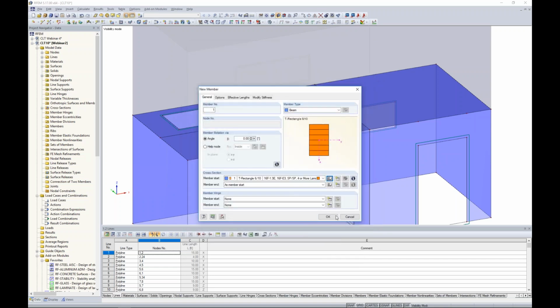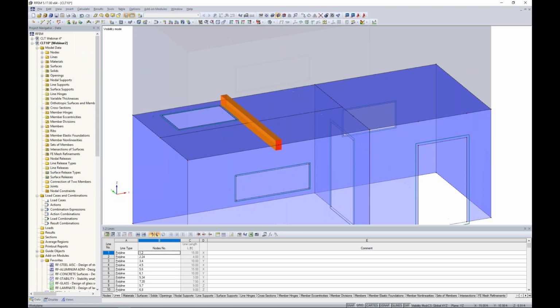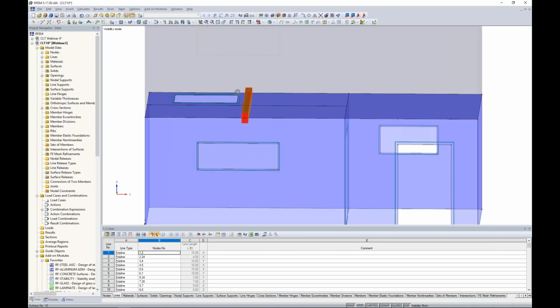So now we click OK through our dialog boxes, and it's as easy as choosing a point to snap on our structure. Now again, the program has nice AutoCAD-like features. So the point that is perpendicular to my opposite node will automatically be highlighted, and these are called O-snap settings. Again, something you'd see similar in AutoCAD. So our beam element was created here.